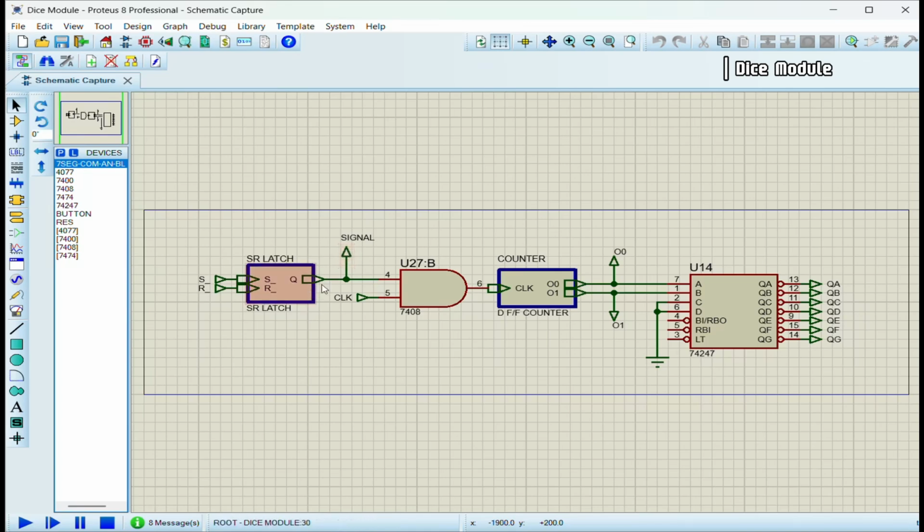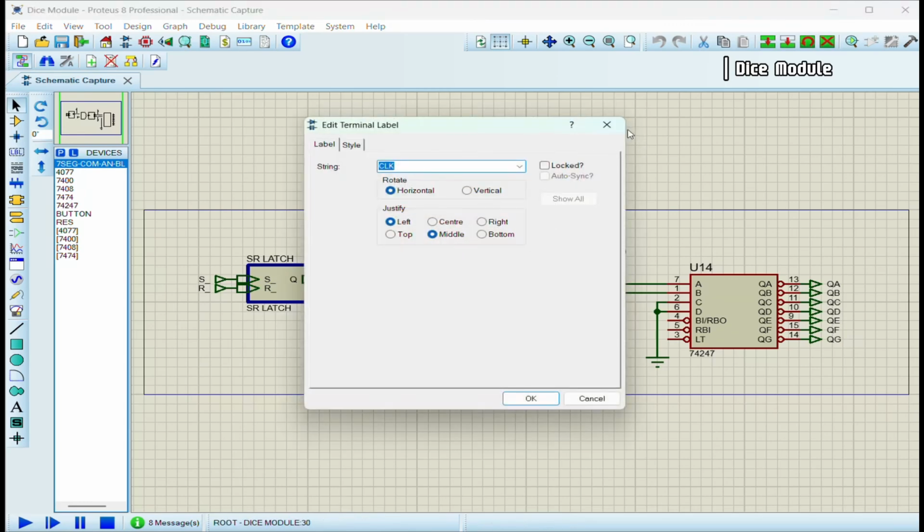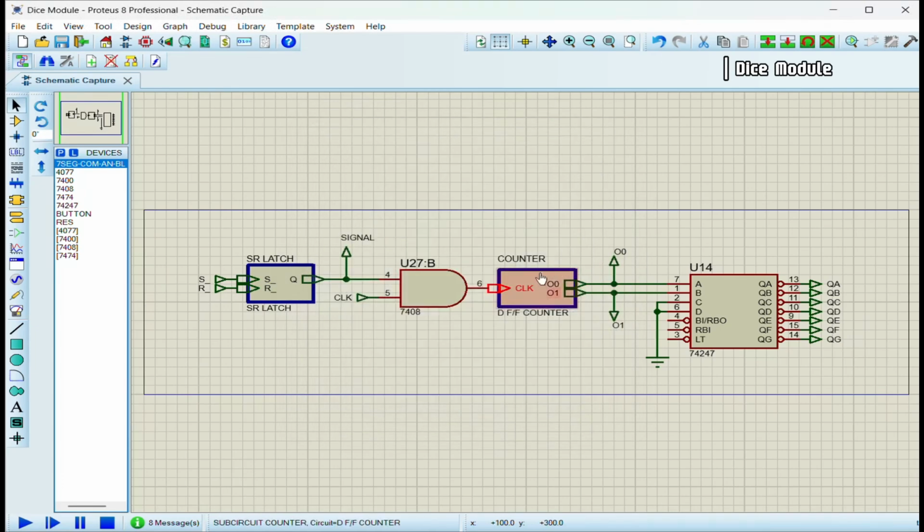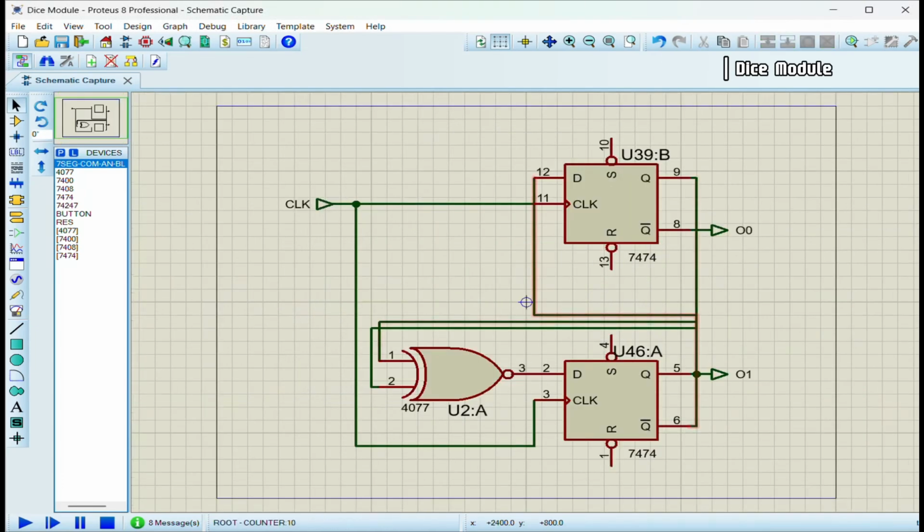Q and the clock pulse pass through an AND gate. The counter of the clock pulse activates. In the counter we use 2 D flip-flops. By using state diagrams, we found the logic of dice rolling and made it in a way where we don't get 0 on our 7 segment display.